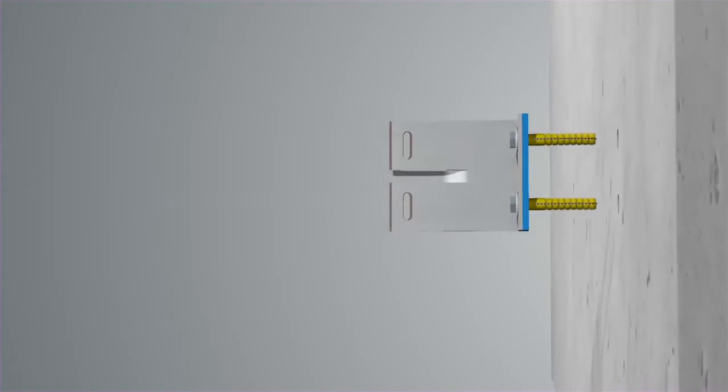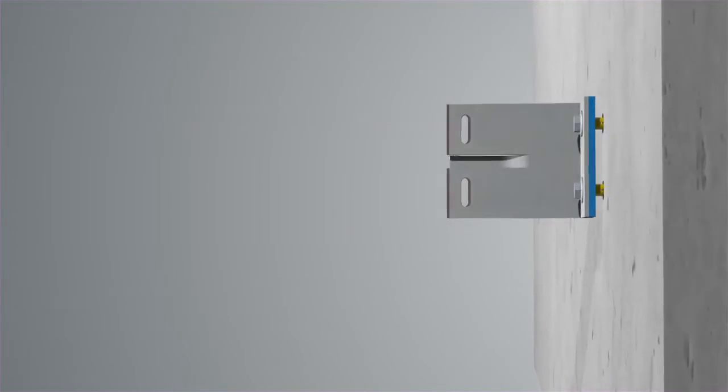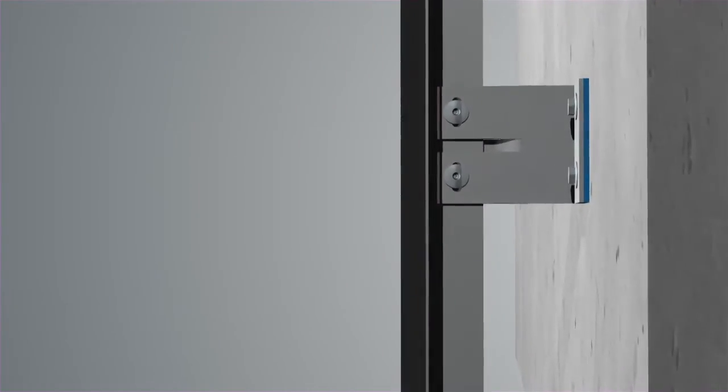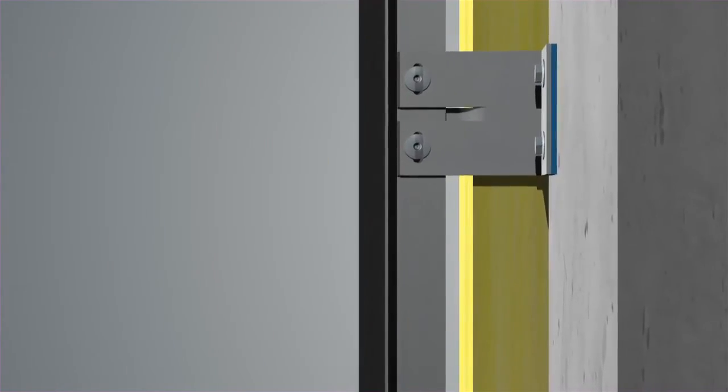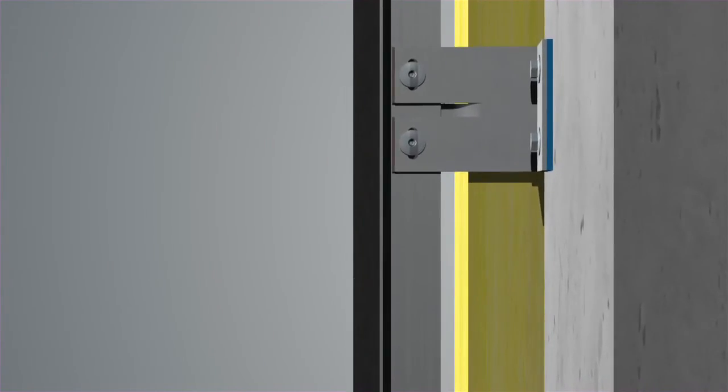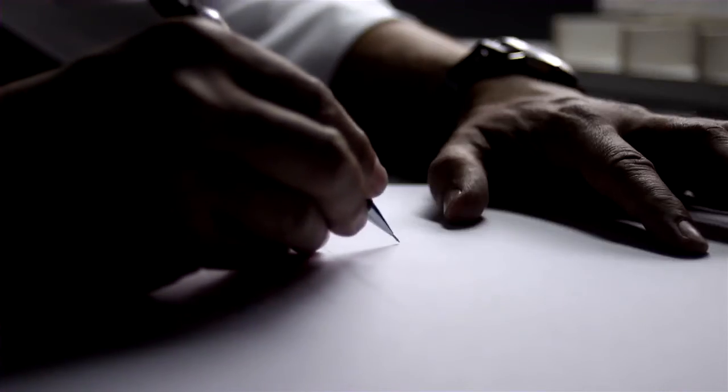Normally, a wall bracket connects the profiles to the wall. The vertical profiles support the panels. This creates a cavity space, which is an ideal position for the insulation. The panel layout can have a big influence on the amount of large or small profiles needed. When meeting the architect early in his design process, it can be helpful to discuss this.